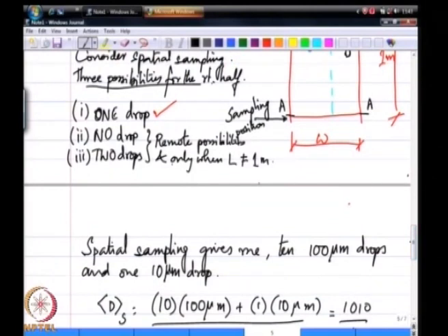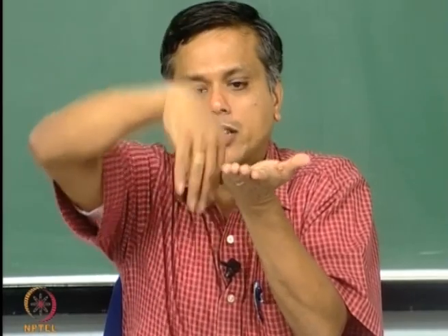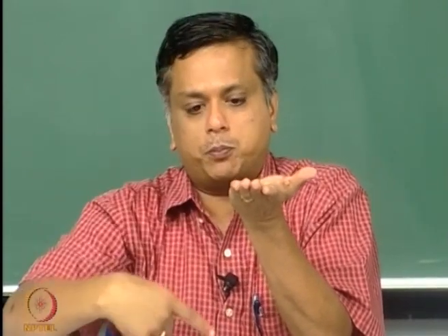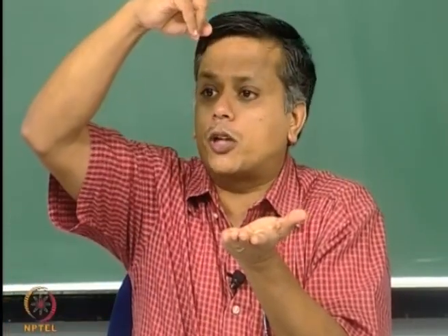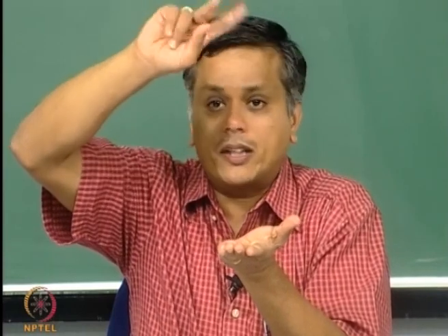Now, you have the sampling, it is like a sampling cross sectional area in which I am allowing these drops to go through. So, every time a drop goes through, I have a way of measuring its diameter. So, the rate at which drops can go through here in a steady spray has to exactly equal the production frequencies. Whatever the production frequencies are, that is what I end up measuring here. Okay. So, what you get in the time sampling in the time domain is basically related to your n1 dot and n2 dot.